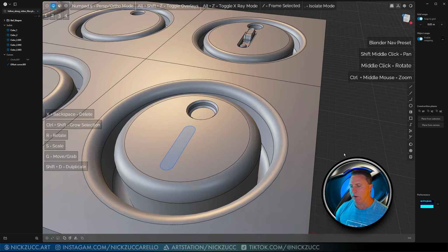And this is going to be called imprinting. So if we do Shift I, we can imprint a curve onto a body. So I selected this curve, hit Shift I. Now it's going to say, what body do you want to imprint this onto? I'm going to select this one here and hit OK. And then now you can see I can turn the visibility of the line off, and now it's actually imprinted those curves or projected them onto the surface. And they're not projected as far as like these curves just sit on top of it.